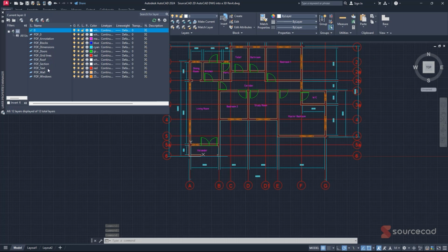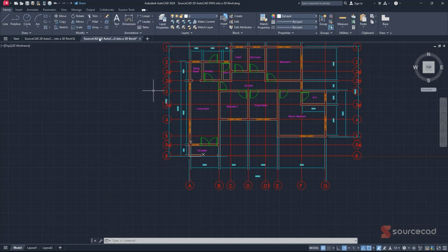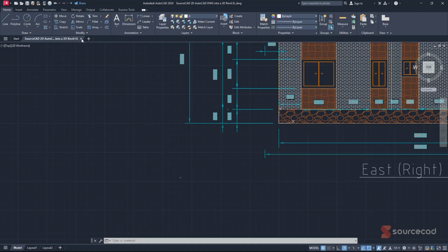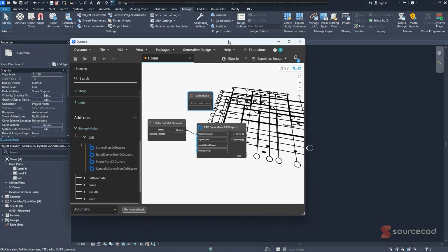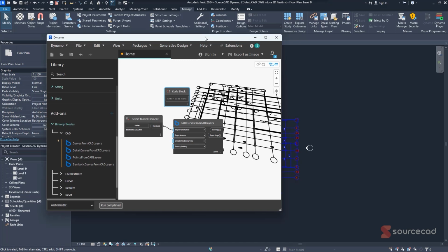So that's the good thing about working with linked. So just click on this, click again, and then just remove the PDF from there, then click away, and then you're gonna just simply close and then just save. So right now it will be reflected in all the other areas that we are running with. So in Revit, we're gonna just simply have it already responded.